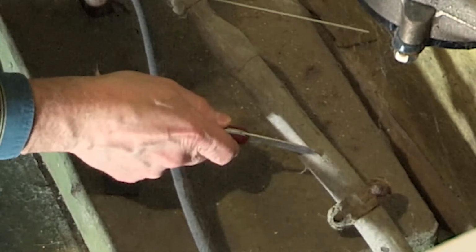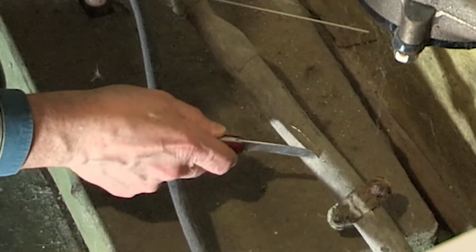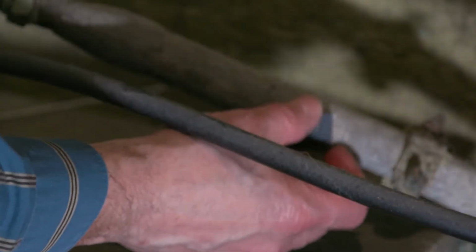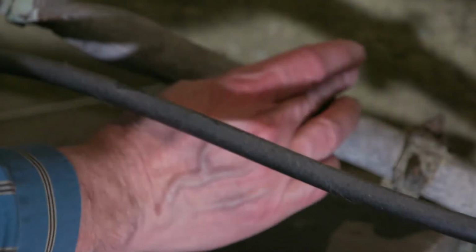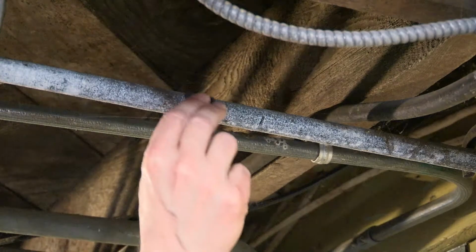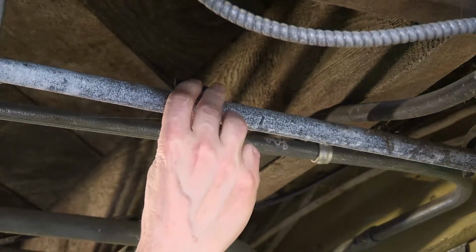Lead is a soft metal and is easily scratched with a sharp object. A magnet will help identify galvanized steel pipe from lead pipes because a magnet will stick to galvanized steel. It will not stick to lead. Assess the plumbing system after the water meter or pressure tank if the property has a private well.